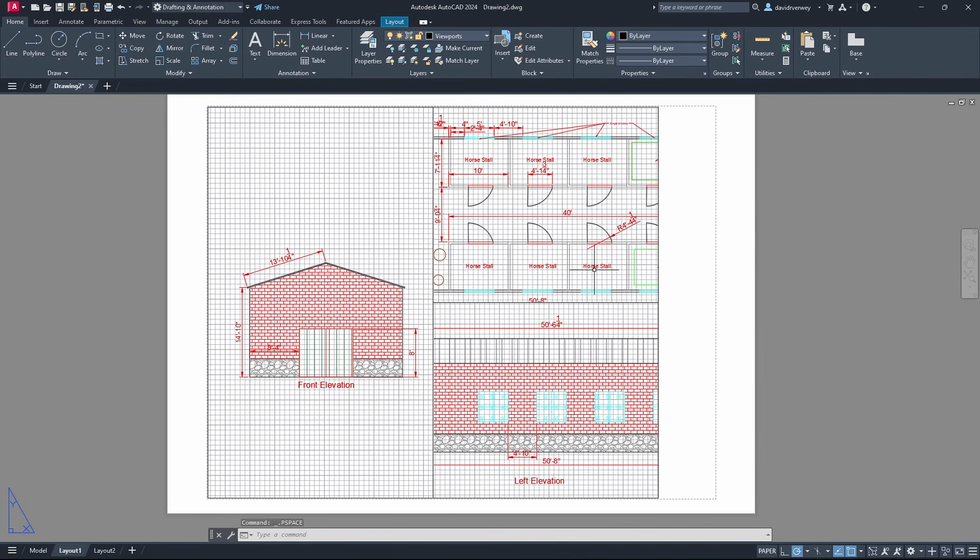One thing to note is when you're clicking into viewports, you have to double click in. To get out, you have to double click out. Escape doesn't work here, because you're moving things in the actual model as well. So you just need to double click out, you need to double click in, and when it's highlighted with a black highlight around it, that's when you know you're in. So double click out and then lock. Always lock your viewports. Make sure your viewport scales are all set to 1:4. When it's locked, it will not change the scale.